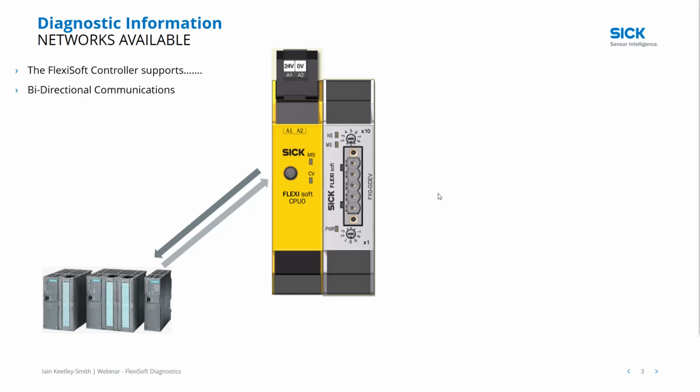So as you can see, the 2 arrows there, backwards and forwards, are grey, and that's just representing the fact that it is non-safe communication that's being transferred backwards and forwards between the PLC. If you do require safe communication between the FlexiSoft and a safety PLC, then we do offer a gateway which allows that to occur. But please get in touch with us if that is part of your requirement.